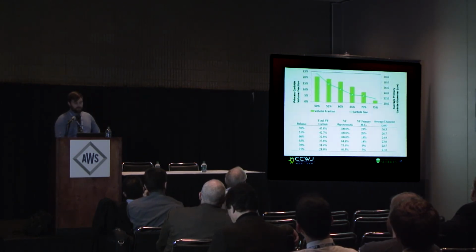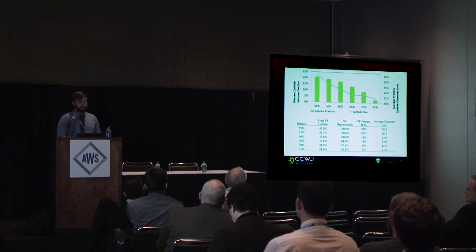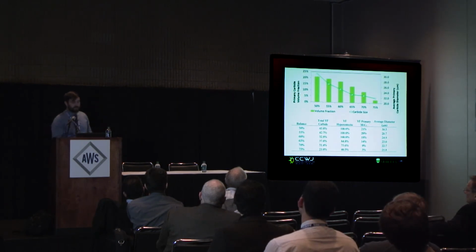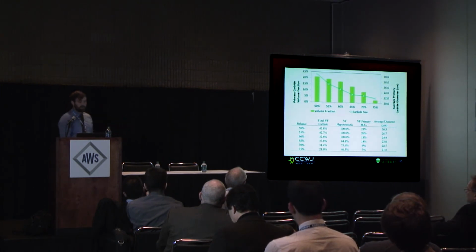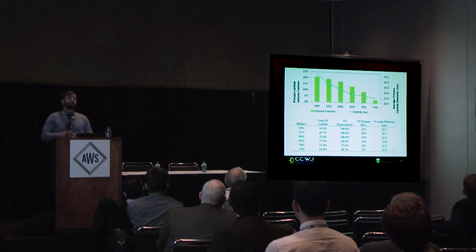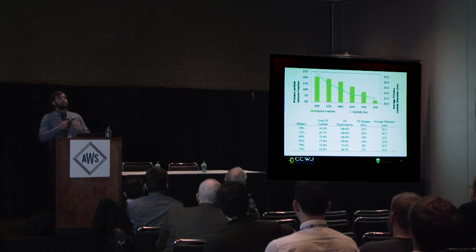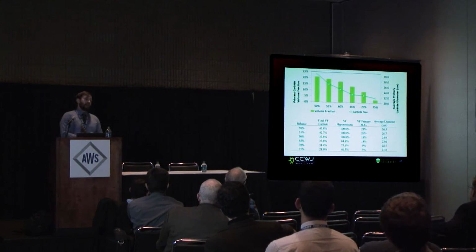Now, the average diameter we also found with the lower balance increased in size, and with the higher balance decreased in size. The one important thing to note too is the fact that we are now getting hypereutectic throughout the entire microstructure. This means good wear resistance throughout the height. You're not going to have good wear resistance at the beginning, then worse wear resistance throughout. So that way you can accurately establish how long your wear plates are going to last.